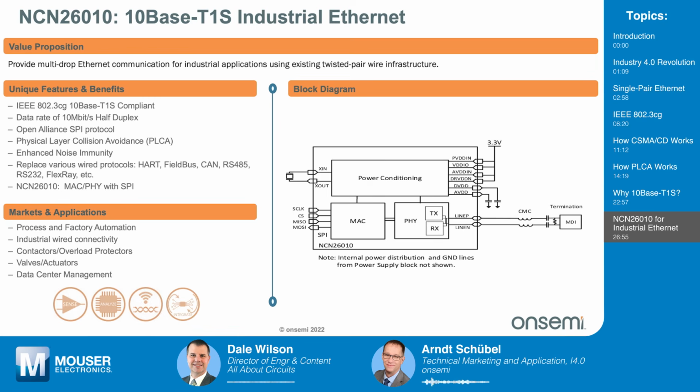We have physical layer collision avoidance. We've shown you how that works in principle, so that's on board. And we have a feature that we call enhanced noise immunity. What that does is it doesn't only look at the signal levels on your cable.